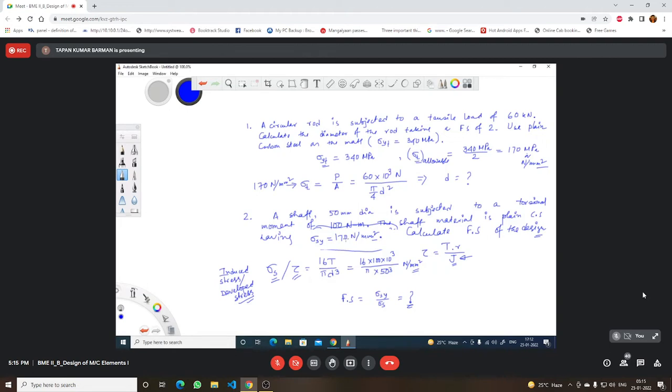What you have to consider at that point when the loading is fluctuating in nature, at that time you need to consider the endurance limit of the component. So when you discuss the strength component, probably you have seen in the presentation, strength is already there. But when we are considering the strength in the design, we should know how the component is loaded. Then only you have to consider that strength, you may make the design of this component. Is it clear? Okay, take the third problem then. Then I think your idea will be more clear.